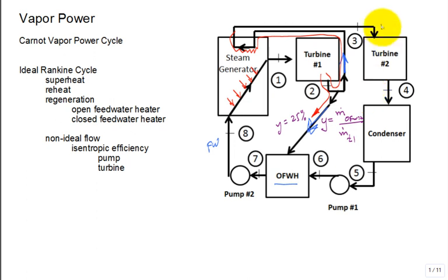And so this would be 1 minus Y going through the second turbine stage, 1 minus Y going through the condenser, 1 minus Y going from the condenser into the pump, and then 1 minus Y coming in to the open feed water heater, Y coming into the open feed water heater, and guess what comes out? 100%, and then you're back to 100% of what goes through the first turbine stage. So you get the mass fractions.